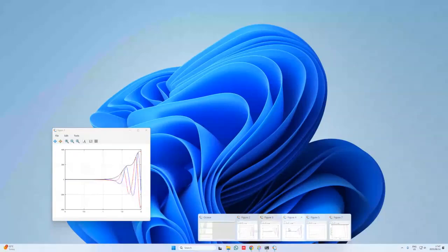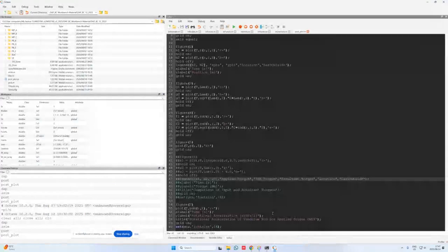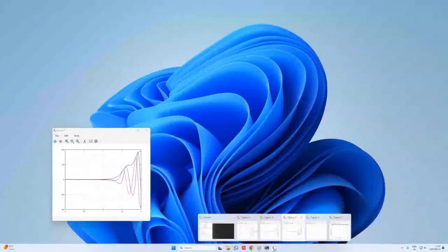Then figure 4 is the actual accelerations that we see for the system. In this case we can see that we are applying constant torque. It doesn't necessarily mean that we're going to get a constant angular acceleration out. As a matter of fact, as we continue to apply this torque, it's actually causing the oscillations in the angular accelerations to grow. So we have higher amplitude oscillations after 2 seconds than what we had at the start. And the frequency of the oscillations also increases. So this shows that the angular acceleration of the pendulum rod is not constant, although we specify a constant torque.